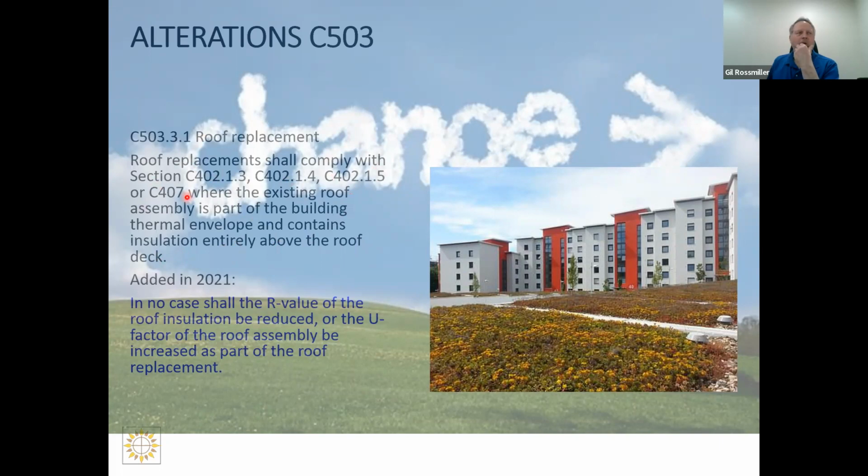And then there's performance, right? It essentially says right there, and rightly so, that was how it ended up. I don't believe that was ever the intent, but that's how it went in. If there was only an R20 on the roof and you have to have an R30, boom, I've got to go to an R30 unless I can trade myself off somehow through a UA calculation or U calculation, or performance.